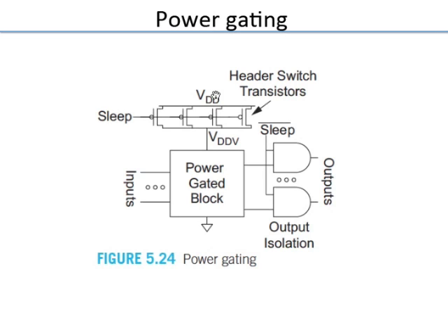Let us say VDD is 1 volt. And when it's running, it's not in sleep, this VDD V is say close to 1 because you did a great job of designing the power switch. When you shut this off, VDD V will... you cannot define it, but physically what will happen, right? It will be some voltage, no? You can say I don't know.